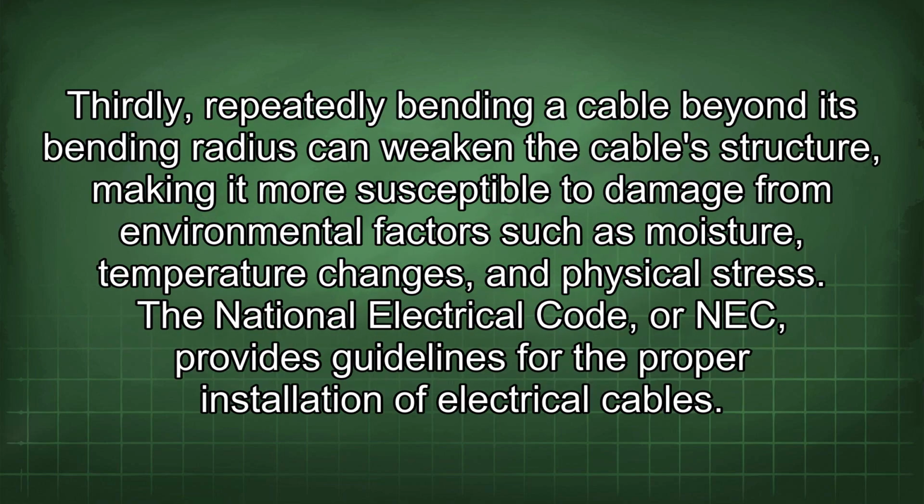Thirdly, repeatedly bending a cable beyond its bending radius can weaken the cable's structure, making it more susceptible to damage from environmental factors such as moisture, temperature changes, and physical stress.